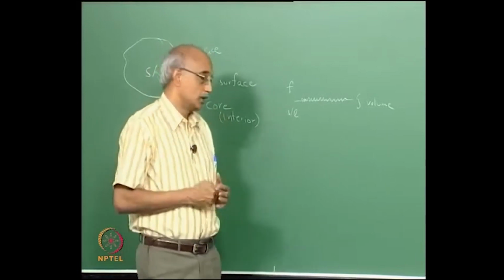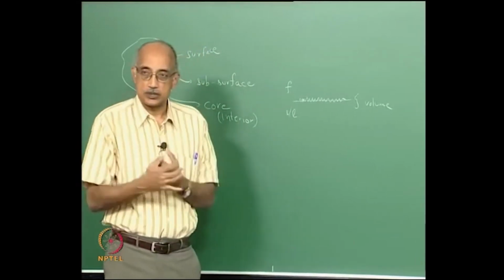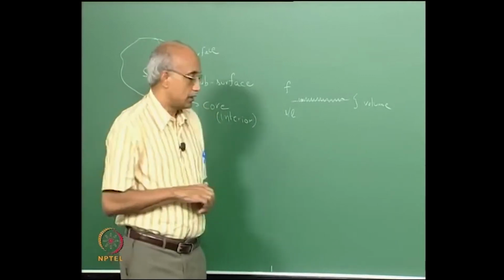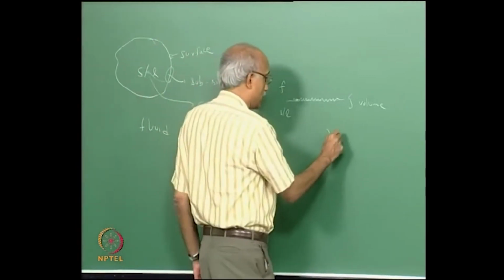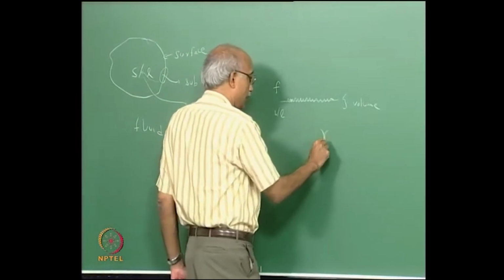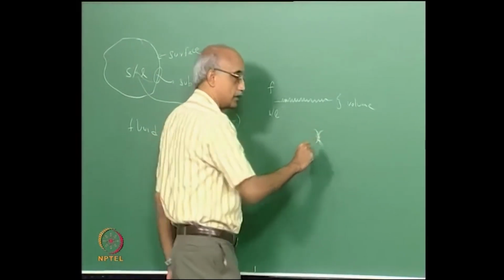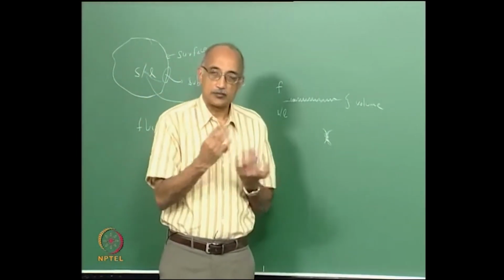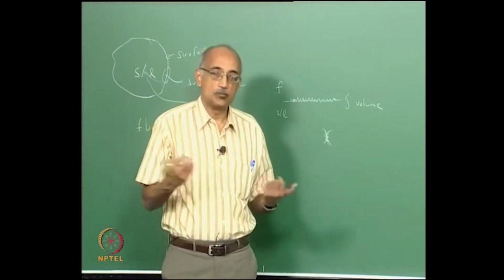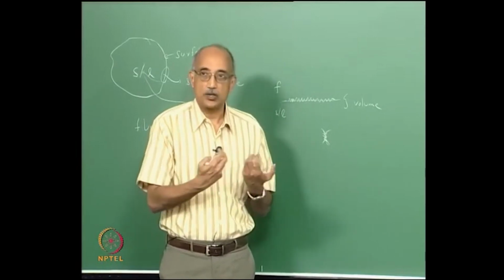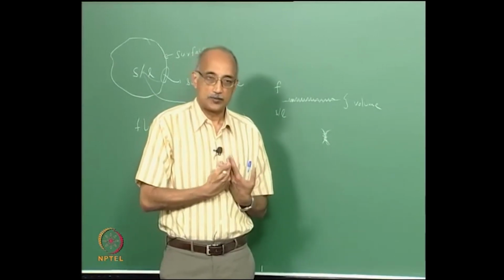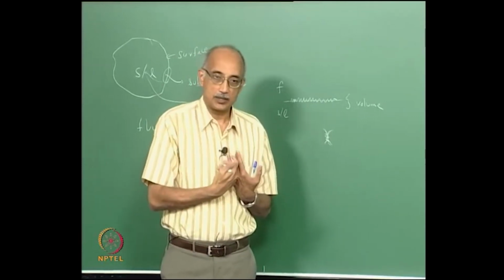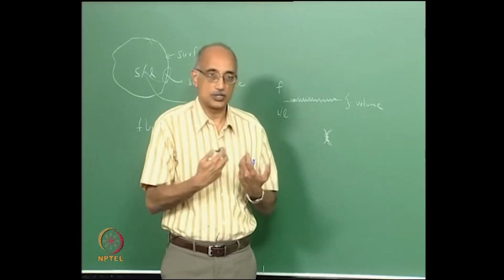And similarly, when you have 2 particles that are close to each other, which are adhering to each other, the interaction between 2 solid particles will again reflect the 3-dimensionality of the particles. So, depending on the relative roughness of the 2 particles, you may see more or less interlocking. For example, if the roughness asperities align with each other, you can actually get an increased surface adhesion force.